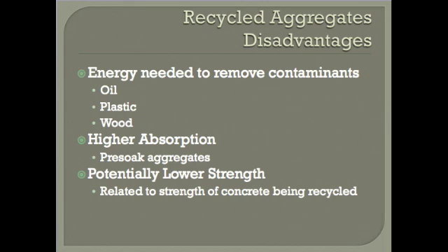There have also been a number of studies on the strength of concrete with recycled aggregates versus traditional aggregates, and there have been very mixed reviews. Some say that there's a significant drop in strength, and others say there's no difference at all. The only consensus has been that the strength of the concrete with recycled aggregates is directly related to the strength of the original concrete that's being used as recycled aggregates.